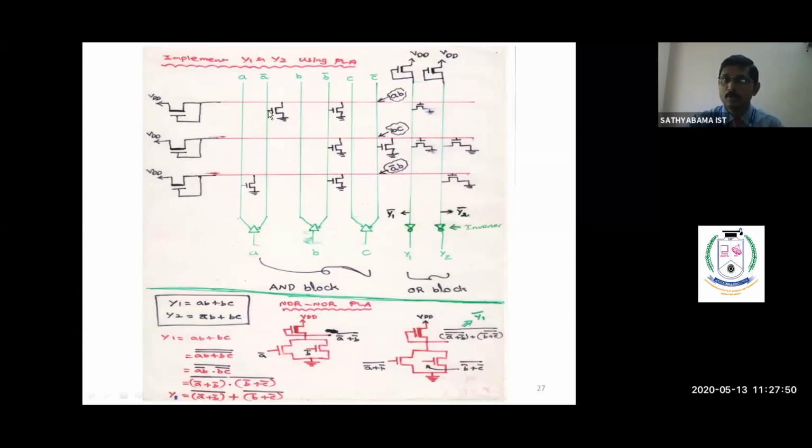So this is the input of the transistor A bar. Other transistor's input is B bar. So this is the B bar line. So here we have to make the transistor. Therefore, these two transistors are connected in parallel, and one end is connected to the output line and the other end is connected to ground. Okay, so the pull down network is completed.